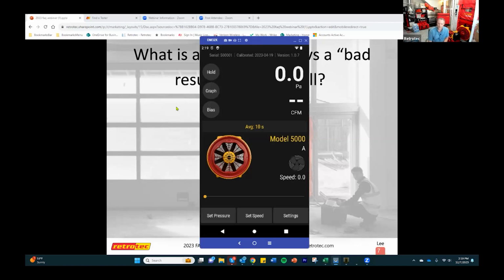So if you really want to nerd out and get into the weeds in that, Joe Stiebert from Building Science Club has a good article that he wrote a while back. To summarize what he said: air leaks through surfaces, not volumes. So it's just a better way of looking at that. But there are some options. If you're not crazy about getting too accurate or into the weeds, you just want a general ballpark idea, you can use ACH, or you can use the floor area square foot method,